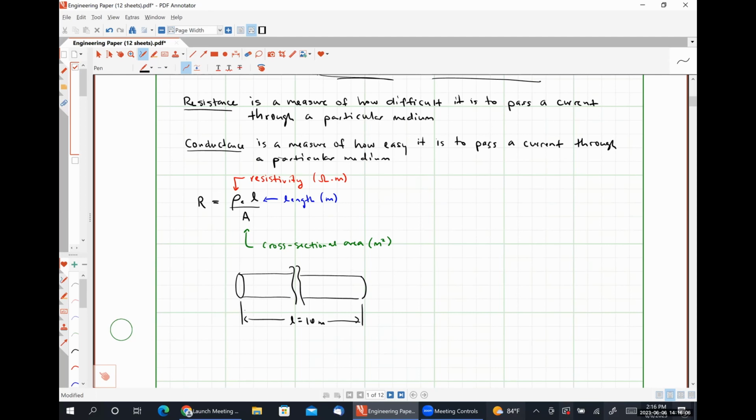And let's say that the diameter of this wire, D, is equal to 1.024 millimeters. This would be typical of AWG, or American wire gauge, number 18 copper wire, which is very similar to the wire that you guys used in your kits and in the freshman series. Okay.